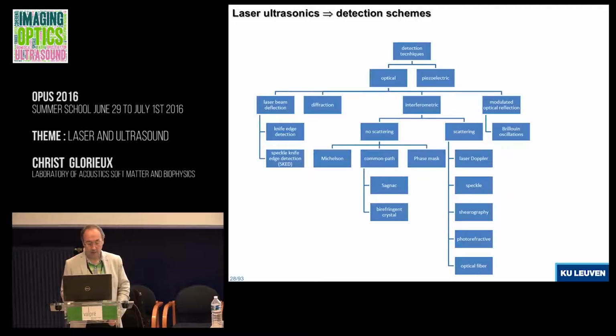I estimated, I just put some rough numbers again, that for example if you have typical strains in biomedical applications with a typical piezoelectric transducer, the piezoelectric coefficient is given here, and I just took it from some supplier. If you put those numbers there, so you put the strain, the piezoelectric coefficient, and the thickness of the sample, then you arrive at some millivolts of signal for typical strains.